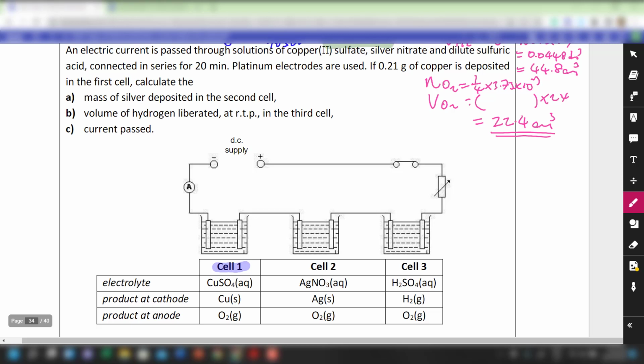Therefore the electrode directly connected to the negative terminal will be the negative electrode. And if this is negative, the other electrode will be positive. The electrode connected to the positive terminal will take on the positive charge, and therefore you will have positive polarity. We continue with this, so the next one will be minus, and then plus and minus. Just make sure that the plus and minus alternate, because if it doesn't alternate, then something is wrong. Your cell will not work. If you don't understand why, please think about it.